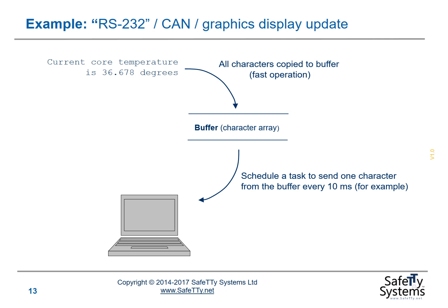very, very short. It takes next to no time to transfer the data to my character buffer, probably a fraction of a millisecond. To transfer my data from the character buffer, one character at a time, to the laptop also takes virtually no CPU time, because the UART buffer that I'm copying the data to will be empty.